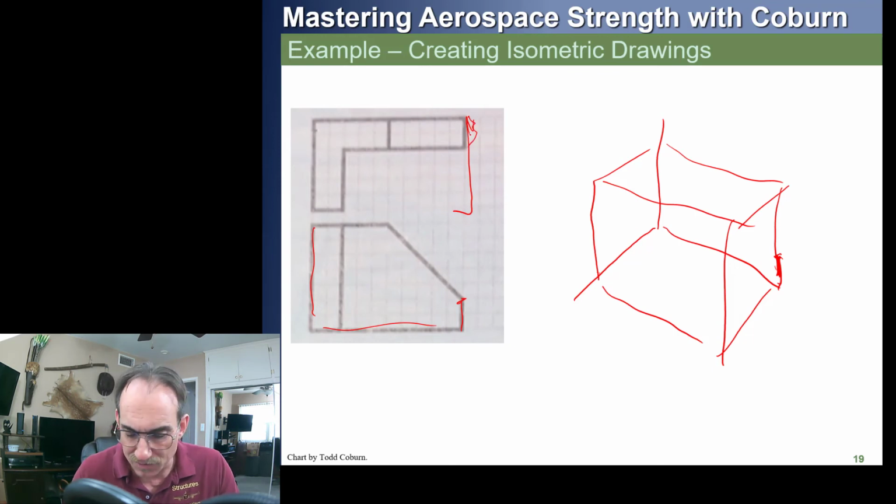I'll take this measurement here and draw it there, so that tells me parallel to this, that tells me where that point is. And then this goes up once again. If we look on the back face, this same width is like this. So wherever that would have hit here is where it hits back here. This is how it's coming.